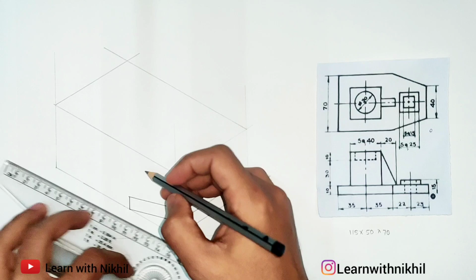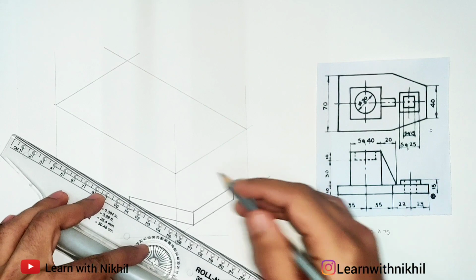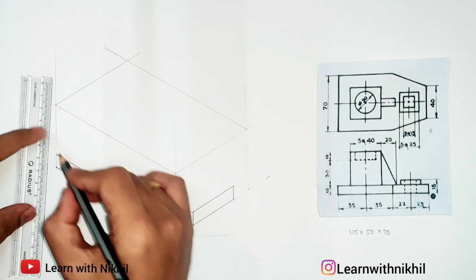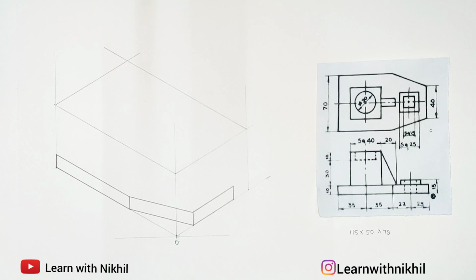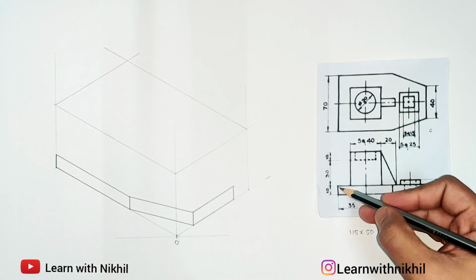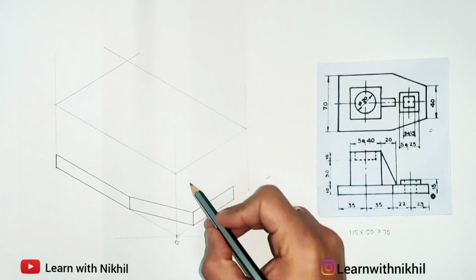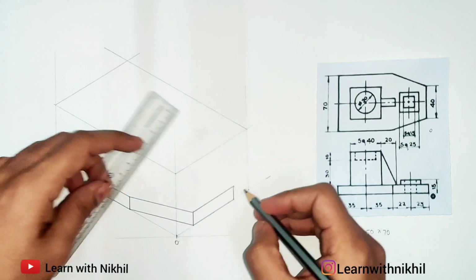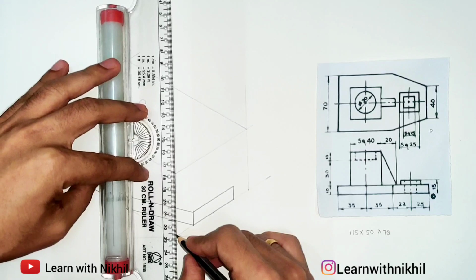So as you can see, this distance is 70 millimeter. You can draw this dark line, and from here also dark. Join this dark, and this part is done. Now the same thing is on the other side also. Here you can see you have a rectangular box. Then here also the same thing it is there. Then you have a square in the front. So this part is at the center line. So you can draw the center line here as the square, and the backward part is at the center.